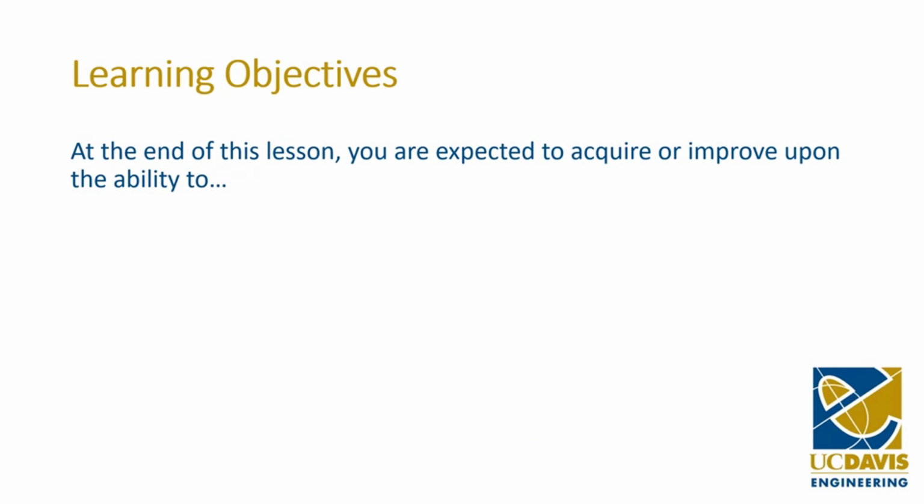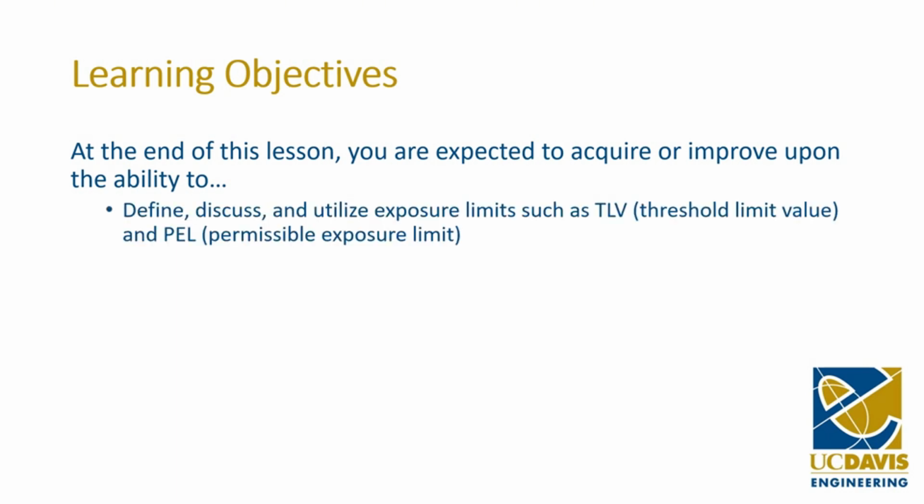The learning objectives for this lesson are that you're expected to acquire or improve upon the ability to define, discuss, and utilize exposure limits, such as the threshold limit value and permissible exposure limit, and understand relative toxicity and its importance.